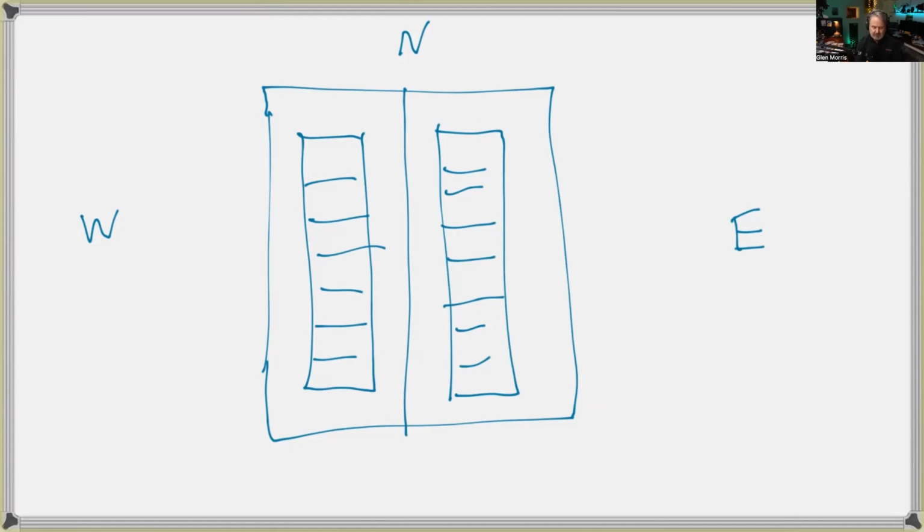So hopefully I don't blow your mind with this, because most people think that if you have two separate strings of panels, a string being a series connection of panels, you need an inverter that has two inputs. Most people think you should be connecting input 1 to one string of panels and input 2 to the other string. But you're allowed to do this, connect them in parallel.